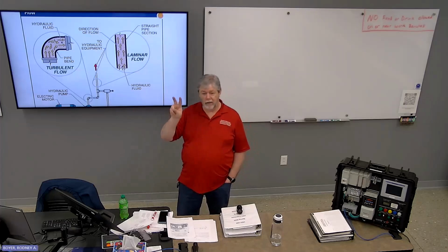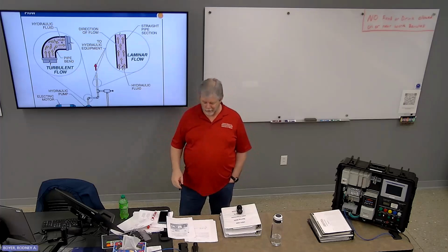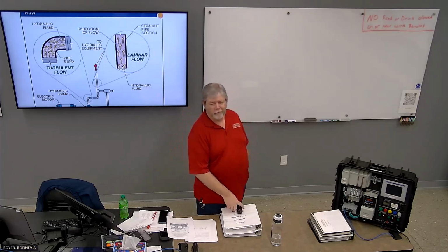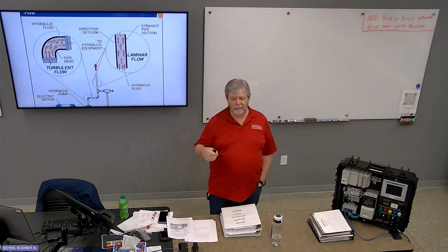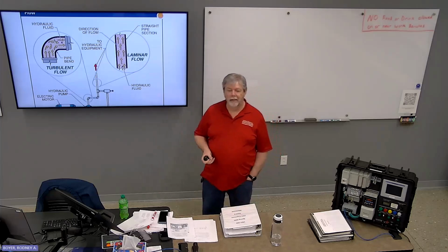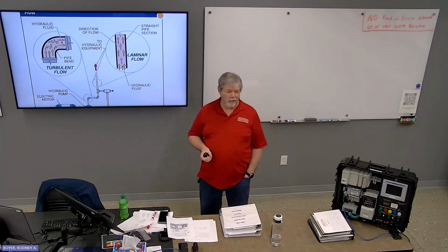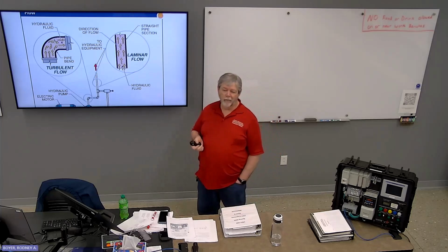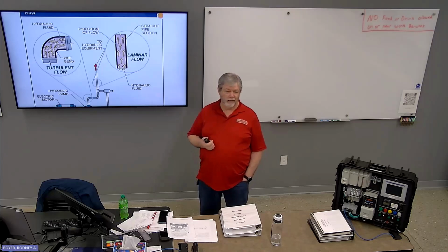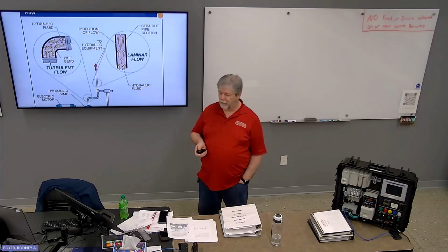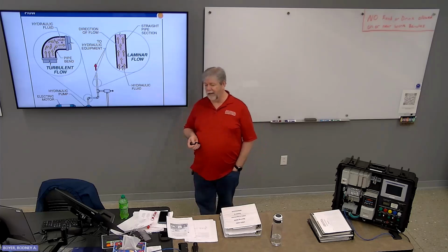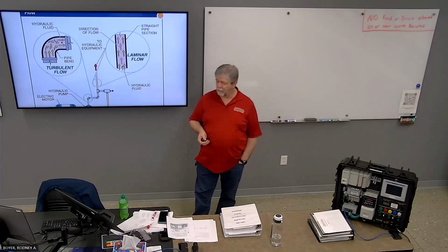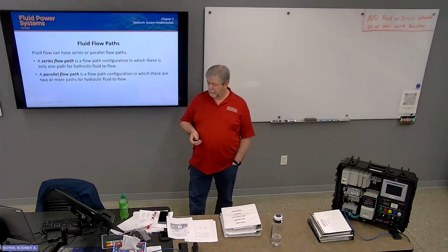That is a loss of energy. If you can't destroy energy, it changed form. So anybody have a guess on what form it changes into? Rick? Heat. It's one of the many ways you can generate heat in a hydraulic system.